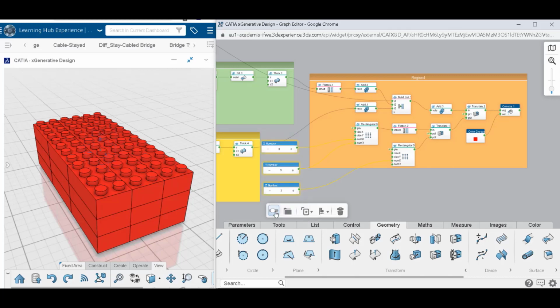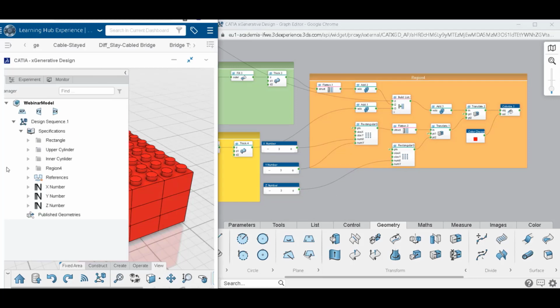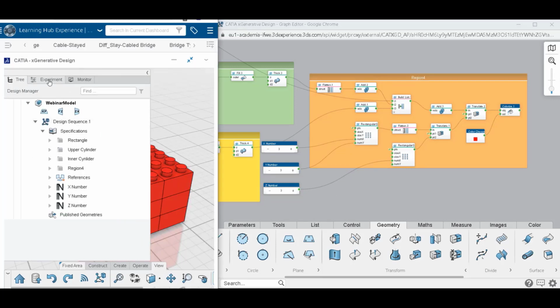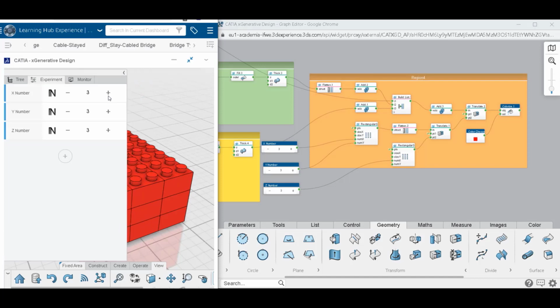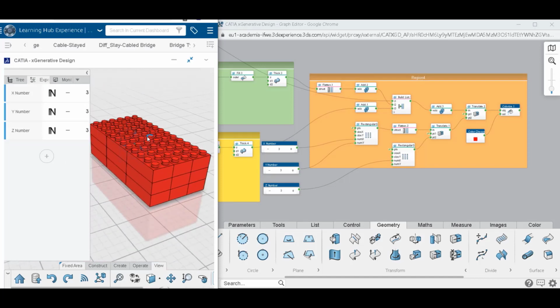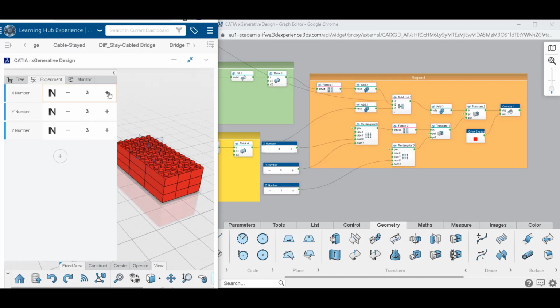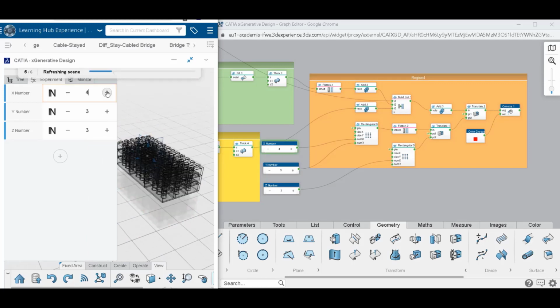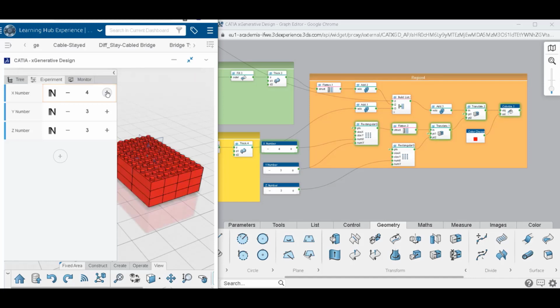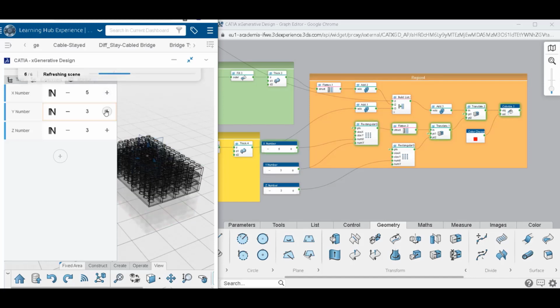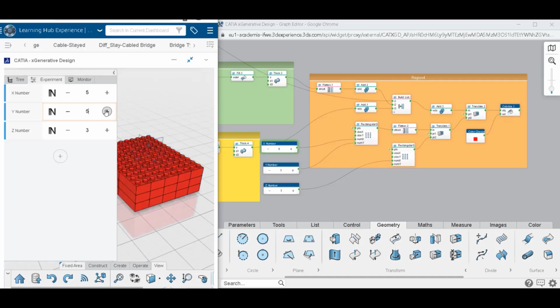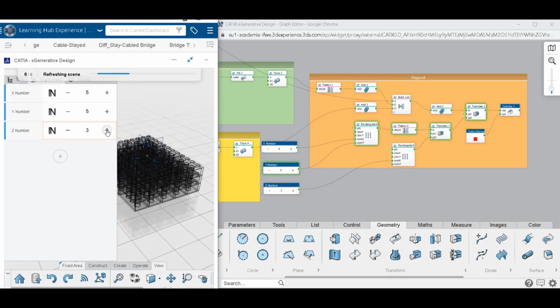We take those 3 commands and we set them as a controller that we can now see inside of the virtual model. In the experiment tab, you have control over the 3 different options that are directly connected in the display graph. If you change this X number, Y number, Z number, they will be directly changed inside of the display graph.